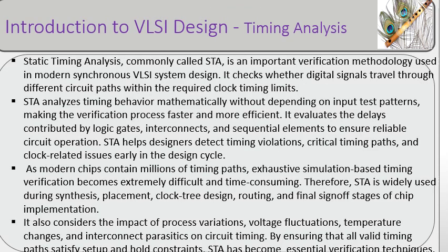Static timing analysis, commonly called STA, is an important verification methodology used in modern synchronous VLSI system design. It checks whether digital signals travel through different circuit paths within the required clock timing limits. STA analyzes timing behavior mathematically without depending on input test patterns, making the verification process faster and more efficient. It evaluates the delays contributed by logic gates, interconnects, and sequential elements to ensure reliable circuit operation.